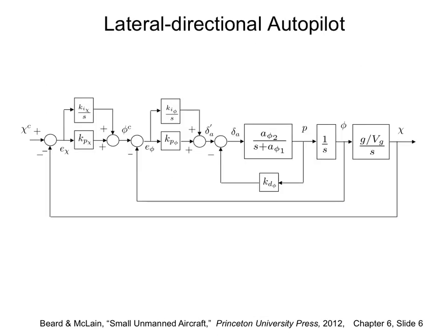Okay, so let's design the first directional autopilot. Okay. So this is the overall gain. So first quantity of interest is this here. So that's your transfer function from aileron to phi, which is the roll angle. So we are interested in first controlling the roll angle, and so the overall transfer function was this multiplied by this, but if you separate them out, you can get P out of it, because we need phi dot to multiply to Kd, right? So you solve in steps.